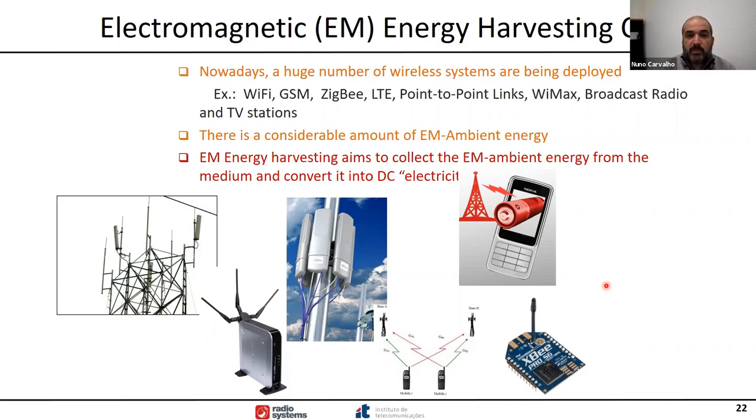What that means is that we already have electromagnetic transmitters around. You have antennas broadcasting electromagnetic waves. You have Wi-Fi, GSM, digital television. Why not collect that energy and convert it back to a small amount of energy that can power small sensors somewhere? When we don't control the source of the energy, we don't call it wireless power transmission.